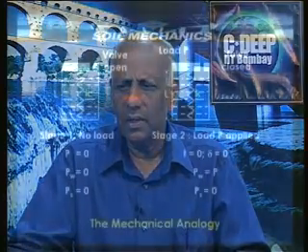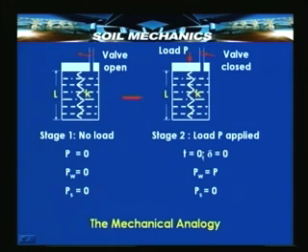Now, if I take the initial state at time t equal to 0, we have just now discussed that at time t equal to 0, the load that is applied is carried completely by the water, only it gets transferred when the valve is opened.